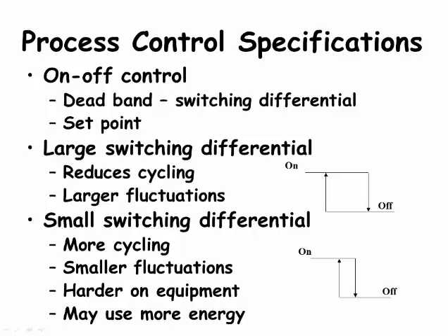We are seeing a move away from on-off control towards more PID control if the device being controlled can be adjusted continuously. A 2013 research report reported that an animal feeding operation using 20 horsepower motors on 2 well pumps using on-off control used more energy than an operation using 2 20 horsepower motors on well pumps using variable frequency drives that ran the pump motors at just the speed needed to provide the water needed.